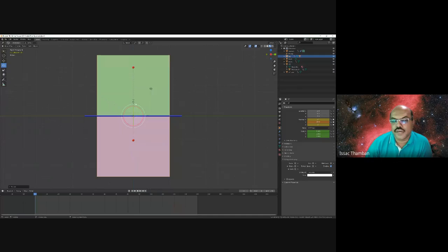This is in the upward direction and this is in the forward direction. So, if a point is located in the first quadrant, then its elevation will be above the XY line and its plan will be below the XY line. Is it clear?